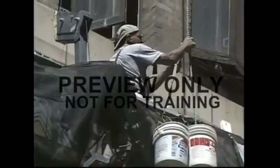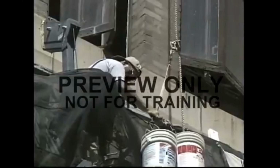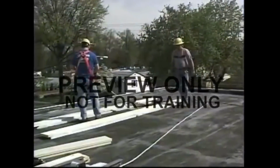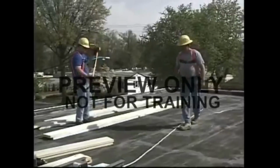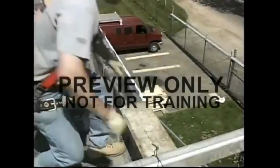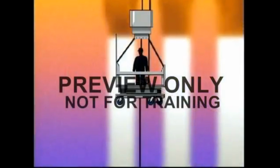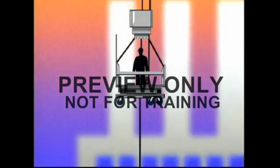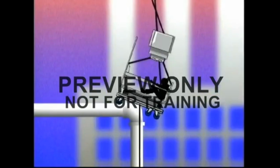There are a number of hazards that you have to be concerned about when working with scaffolds. To start, it is important to check the area where your scaffold will be used before you even begin setting it up. Look for things that could block the scaffold's path while it is in motion. Protruding objects, like pipes and construction equipment, could very well tip the scaffold as it passes by.